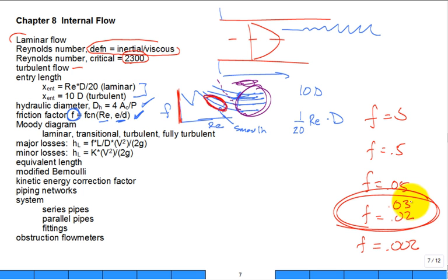little high actually, but you can almost guess one, because if you have to solve some problems, often you have to iterate numerically, and then if you're iterating with the Moody diagram, it's a real challenge. You don't know the fluid flow speed, hence I don't know the Reynolds number, hence I don't know the friction factor. Well, probably best to guess a friction factor and then start the cycle of iteration that way.